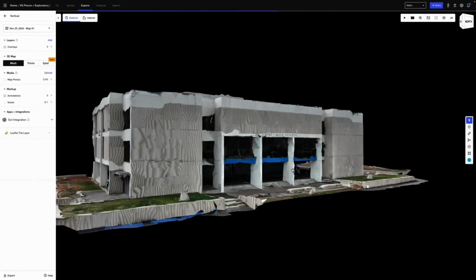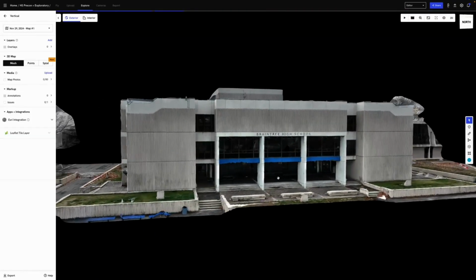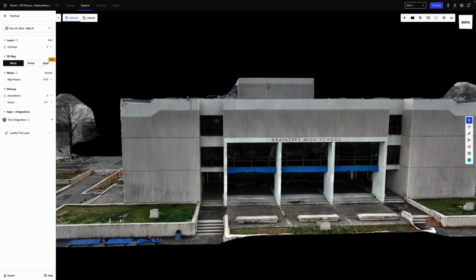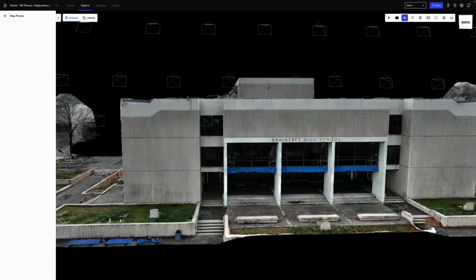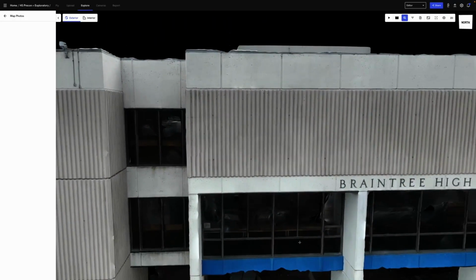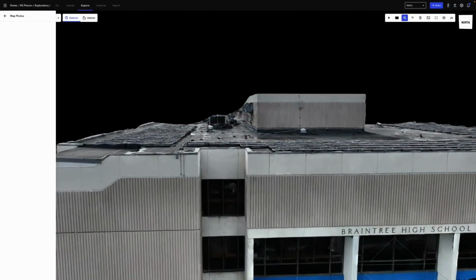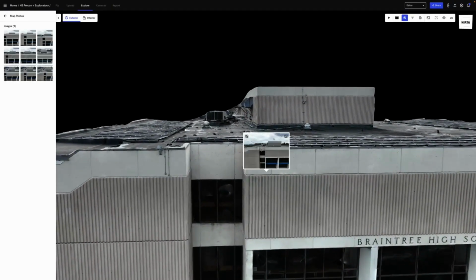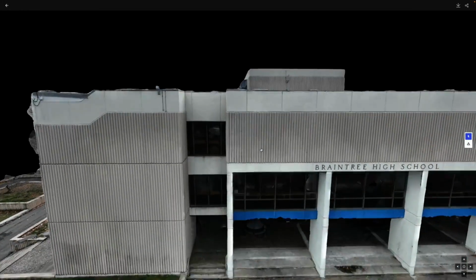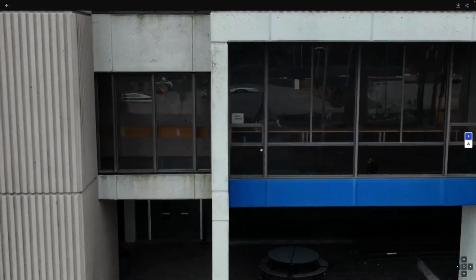Vertical inspections work a lot like models in terms of navigation. I typically will use a vertical inspection to visually inspect various components on the exterior of a building, tower, bridge, dam, or similar. I use the inspect tool to find raw images for a higher definition. I use the inspect tool when I'm inspecting for various components on the exterior of a building. I would like to find the raw images. I can use the keys on my keyboard to navigate around and perform visual inspections.